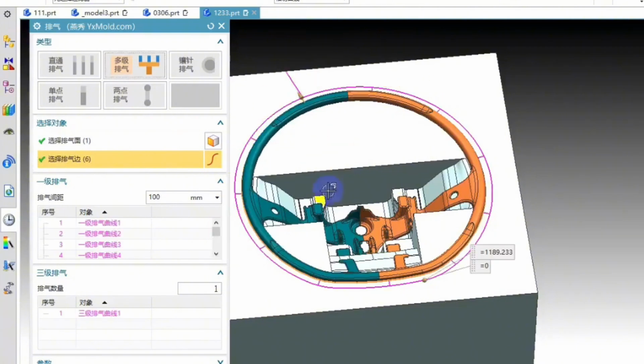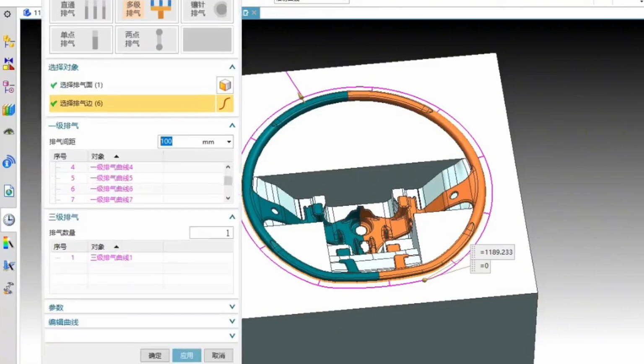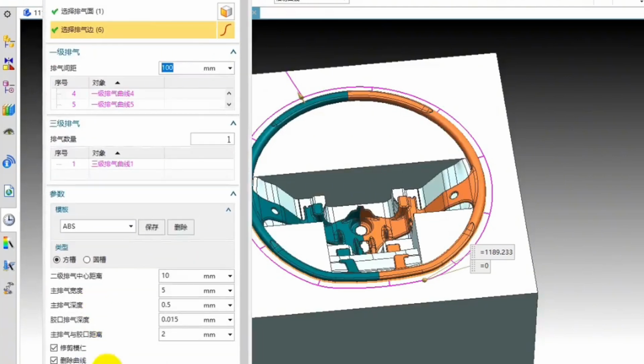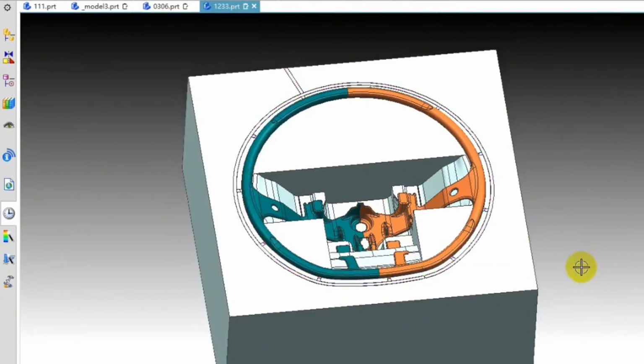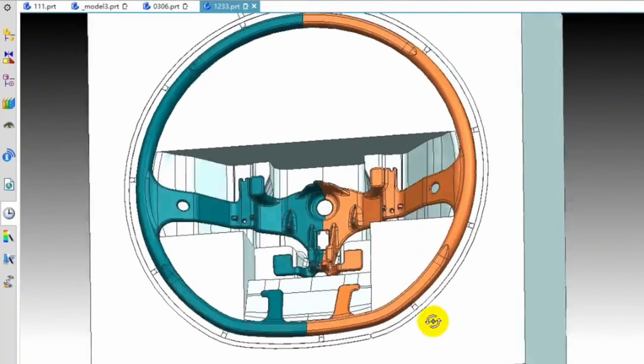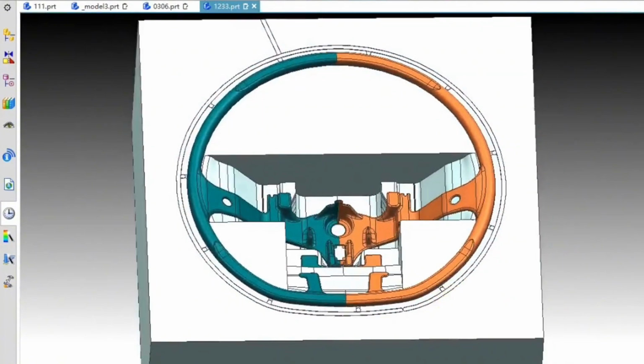The venting effect can be improved by setting up venting slots on the parting surface of the mold, at the fitting of inserts, or by using gas-permeable steel. For example, an air venting groove with a width of 0.03 to 0.05 millimeters on the parting surface can effectively vent air in the cavity and volatile gases produced by the plastic melt.